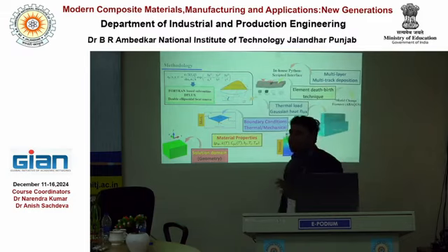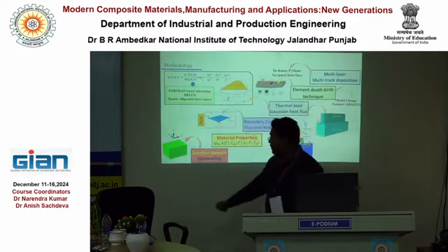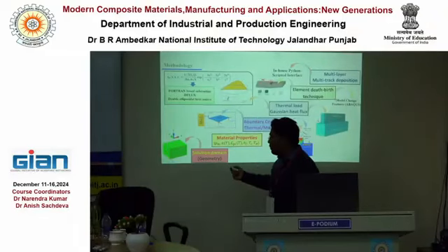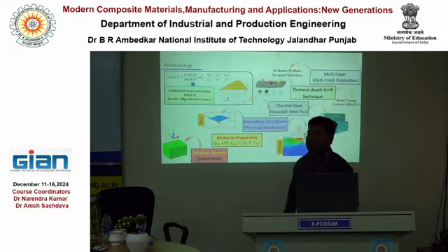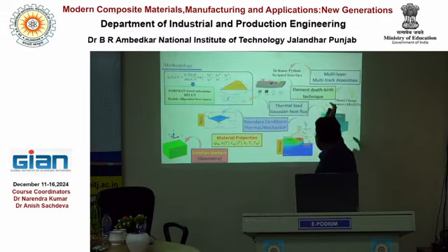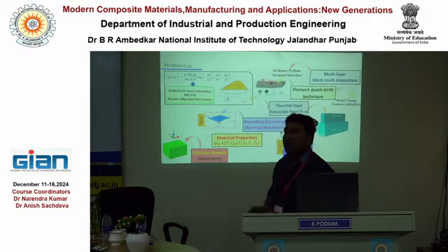On the basis of that, we have incorporated the element death and birth technique. Since we are dealing with a lot of material deposition, suppose the product is 10 by 10 by 10 mm and we are depositing layers of a micrometer only, a lot of layers will be there. It is too hectic to deal with so many layers manually in Abaqus. So we in-house developed a Python script to deal with a lot of layers in one go.